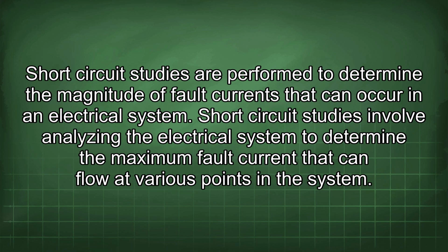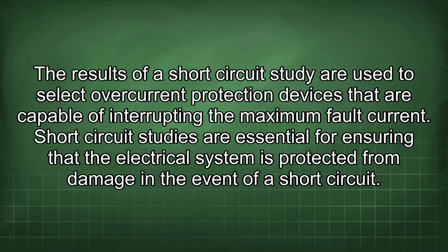Short circuit studies are performed to determine the magnitude of fault currents that can occur in an electrical system. Short circuit studies involve analyzing the electrical system to determine the maximum fault current that can flow at various points in the system. The results of a short circuit study are used to select overcurrent protection devices that are capable of interrupting the maximum fault current. Short circuit studies are essential for ensuring that the electrical system is protected from damage in the event of a short circuit.